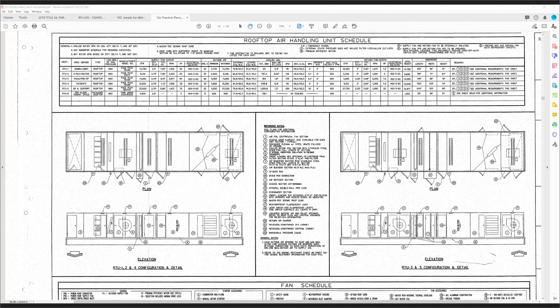All right, great. I'm an electrical and mechanical engineer too. So I think the answer was correctly given. A was the right answer. And my reason is, of course, the mechanical contractor can specify that the rooftop unit should have one source of connection for several reasons. One is the manufacturer wants to wire it that way, and they want to have both supply and return at the same unit to be able to interlock them correctly and all of that.